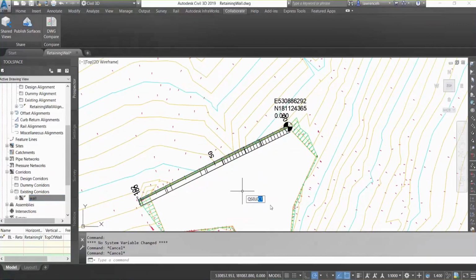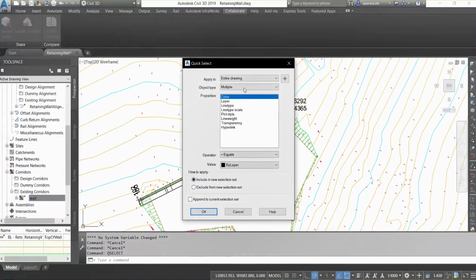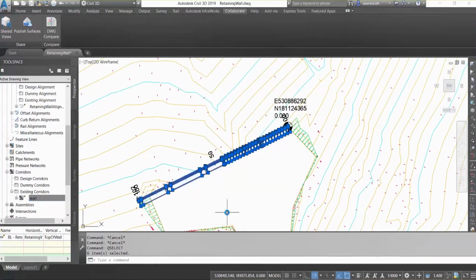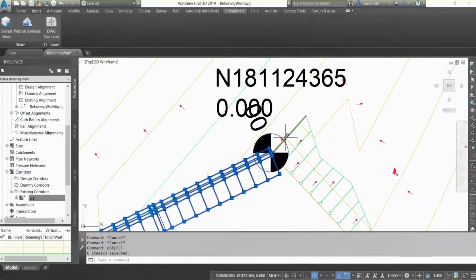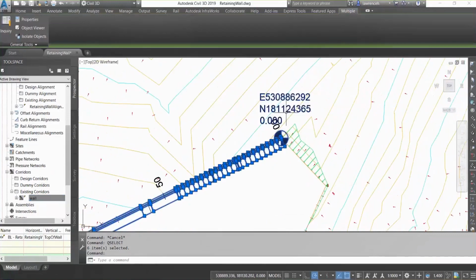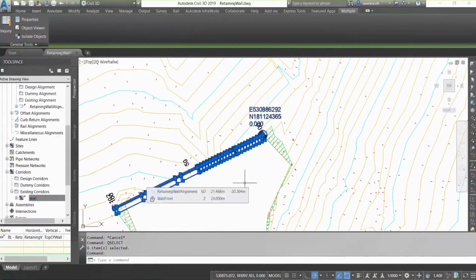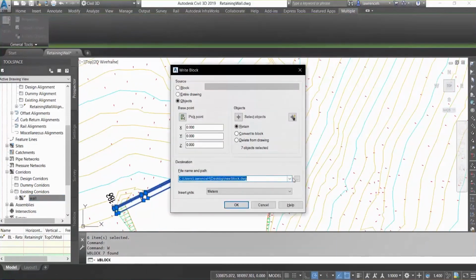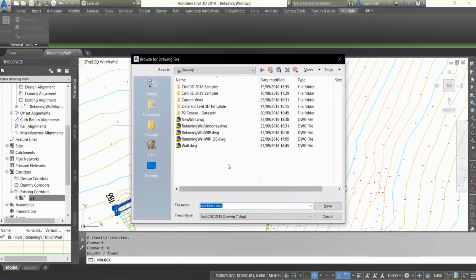The next thing we're going to do is steal that solid geometry from Civil 3D. We're going to select all the solids, which will be the corridor solids from Civil. Notice I'm also picking the datum as well. That's the source of truth, so I'll know where that is inside Revit. It's important to do that when you take information from Civil. You've got to make sure that you have a common datum.